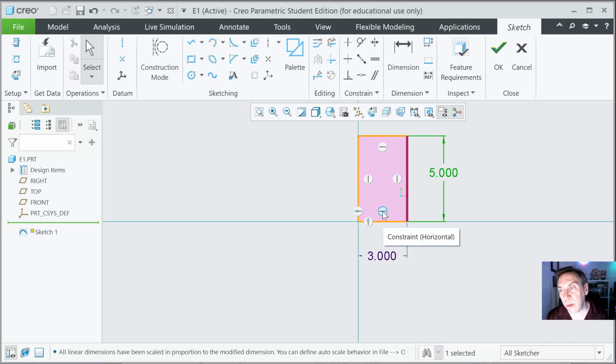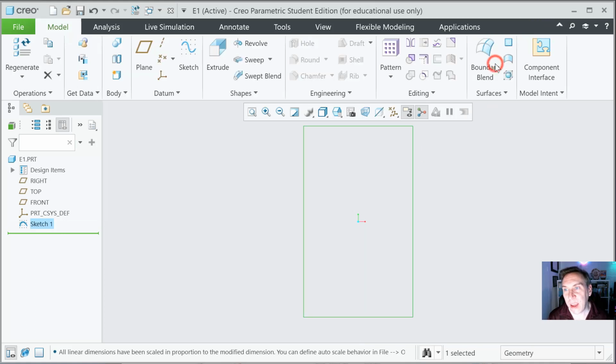All right, now you have constraints, horizontal and vertical. Now, if I were to delete these, you could just click on them and hit delete on your keyboard. You'd be able to move the line at an angle. But right now it's stuck vertical and horizontal, and that's actually what we want. That's the good thing about constraints and parametrics. You can see we have a whole array we could choose from up here. We also have dimensions, so we could have added them manually too if we wanted and overwrote those. Okay, so we have our parameter set. Let's go ahead and hit OK.